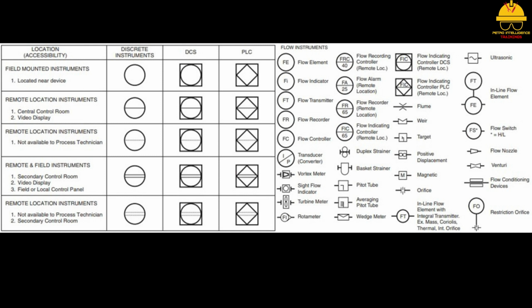High pressure and low pressure sides are located on each side of a pressure capsule. The orifice plate creates an artificial low pressure situation inside the pipe that can be measured and transmitted to a controller. Fluid flow is typically controlled with a flow control loop, FIC. In this system, each of the 5 elements of the control loop will be flow related and labeled appropriately. It is also possible to have other flow symbols like flow recorders, FRs, high flow alarms, HFAs, and low flow alarms, LFAs.